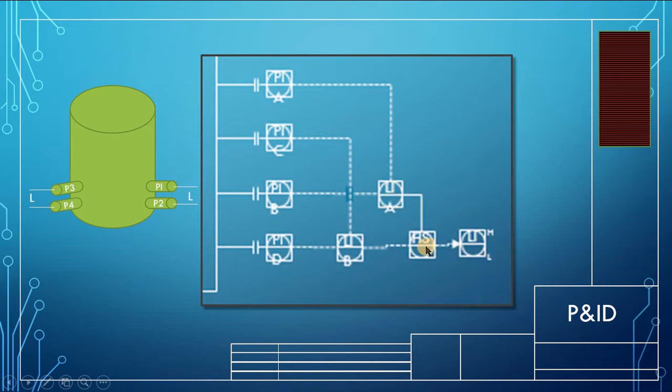You have a selector switch. The operator will select one of them as the tank level, and this new tank level, a new tag, will be used for generating the alarms and everything. So this is your tank level, not this one or this one. But assuming you have a problem with one of the nozzles, that means this reading is not reliable anymore. So the selector switch will go to the second one.